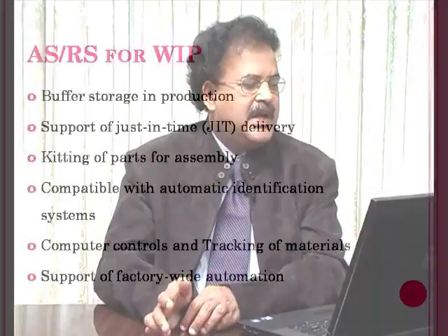This WIP is a raw material on which certain operations are performed, and it is waiting for certain operations to be done on it. And such kind of WIP, when the waiting time is in days, has to be sent back to the warehouse, the storage or retrieval system, and it will be picked up as and when it is required. Otherwise, the entire space between the two machines gets filled up with the WIP, and there is no space for work. So ASRS will take care of this kind of thing.